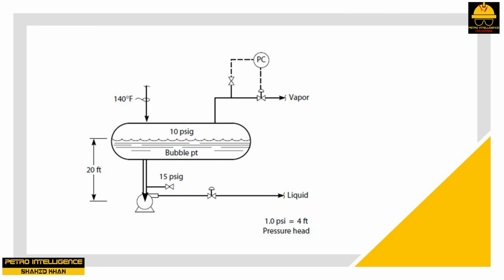Try this test. To illustrate what I have just explained, try this experiment. 1. Open the suction valve to a pump completely. 2. Crack open the case vent to fill the case with liquid. This is called priming the pump. 3. Open the pump discharge valve completely. 4. Push the motor start button. 5. Observe the pump suction pressure.